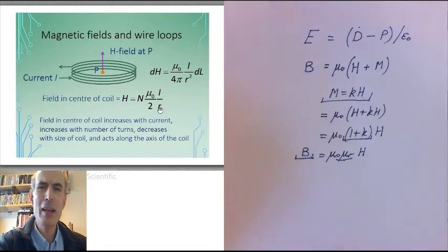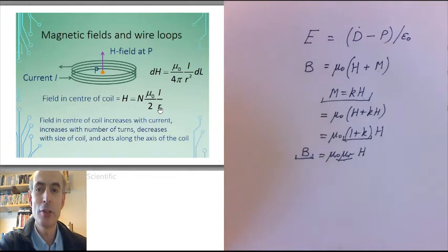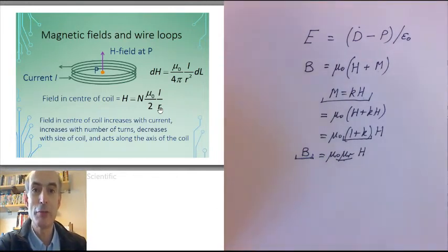It's not just the magnetic field in the centre of the coil that produces an EMF in the inductor, it's all of the magnetic field flowing through the coil. And a smaller radius results in a smaller area in which the magnetic field can be produced. In fact, to get a larger inductance, it's better to have a large value of radius so that the area of the coil is greater and a greater total magnetic field can be generated.